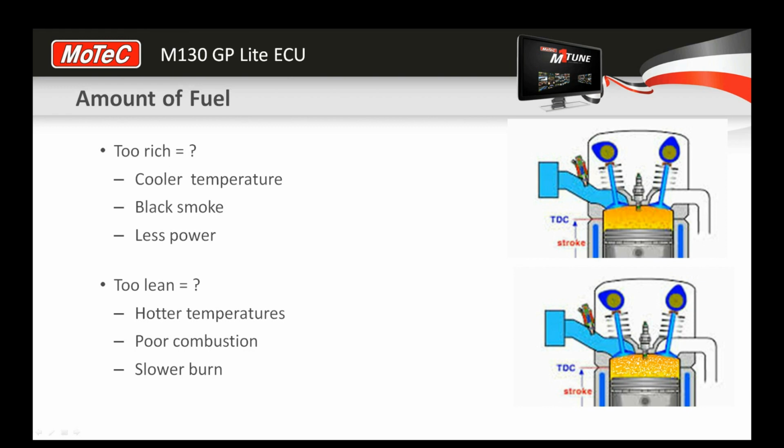So the leaner the mixture, the slower the burn. The richer the mixture, the faster the burn. Again, just generally. Alright, so if we're just tuning for safety, we definitely want to be on the safer side, and as much as 0.9 lambda might be perfect power, on a turbocharged engine you often need to run richer than that, to maintain enough cooling on the piston and to prevent detonation.